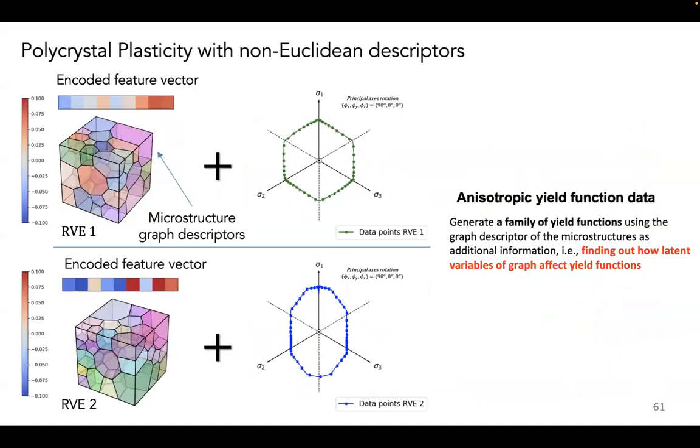The last thing I want to talk about is that if you have an anisotropic plasticity, you can still use the pi-plane to simulate the yield surface. However, what you get in the pi-plane is just one instance. I'm fixing a particular orientation and I create a constitutive law.